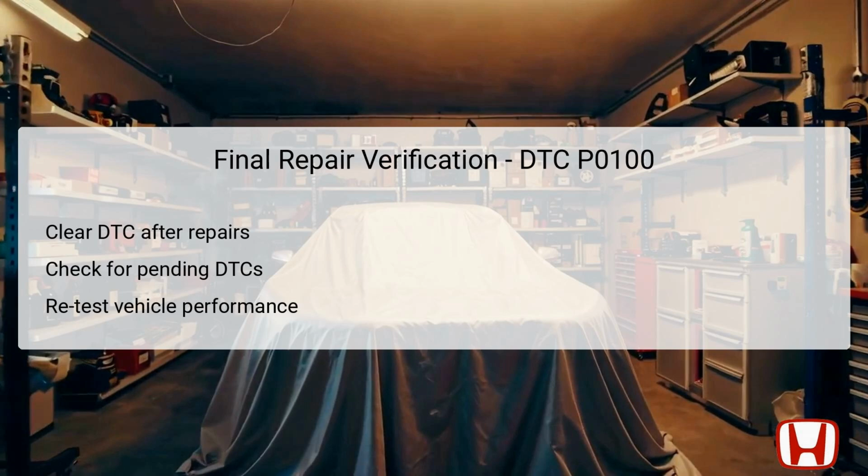Perform a road test under normal driving conditions to assess the vehicle's performance, ensuring there's no sign of the previous symptoms such as rough idling or poor acceleration. Confirm that the MAF and IAT sensors are providing accurate readings and that the vehicle operates efficiently. By effectively verifying repairs, you ensure the long-term integrity and functionality of the vehicle's engine performance.